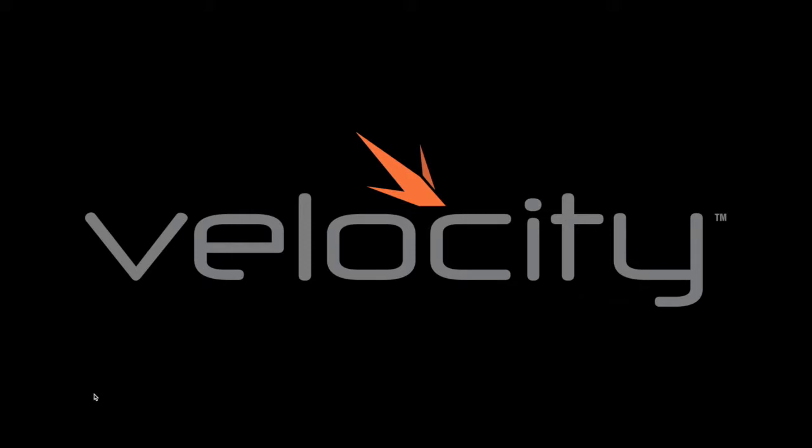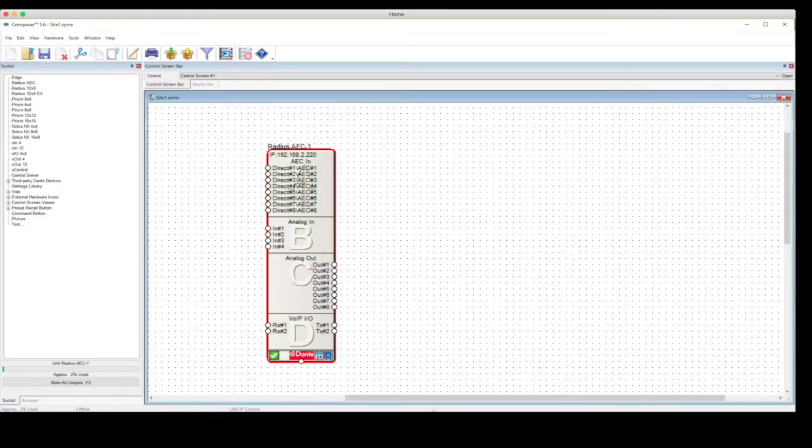And today I'm going to be going over how we can integrate the Symetrix DSP audio platform with the Velocity control system. I'm first going to start off by working with the Symetrix Composer software, and I'm currently connected to a Radius AEC frame at 192.168.2.220. I'm first going to start off by setting up various controls, in particular the fader for an analog output and mute buttons as well.